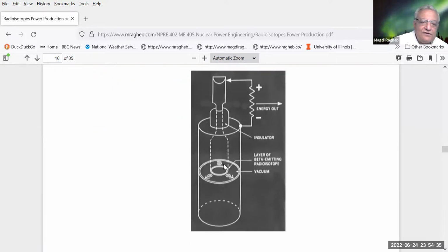So all you do there is get a material that is emitting electrons. So a radioactive isotope like tritium or like thallium-208 or maybe even strontium-90 is emitting electrons. So you have the device here, maybe the size of a 1 centimeter cube for nanotechnology applications. The electrons are emitted. You collect the electrons from an emitter on a collector, and just put your electrons into an external circuit. There is a problem there that you would encounter, is that the electrons usually are emitted at an energy in the kilo electron volt range.